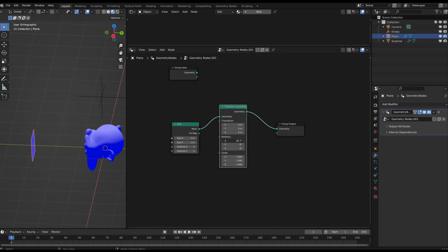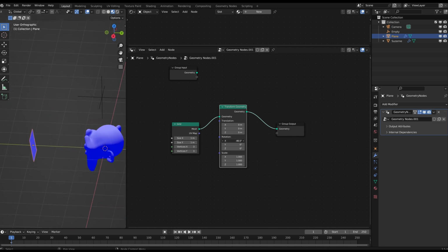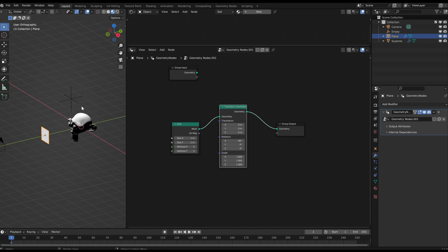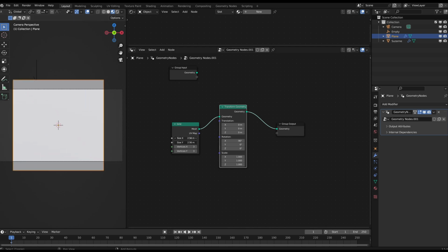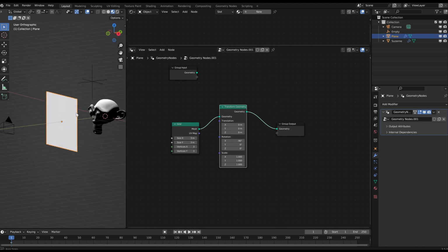Then I can see in which direction I want to rotate it, because I want to cast rays in this direction. So I want to use the blue face here, the correct face. So I use -90 degrees, and now it's oriented correctly. Now I want to increase the scale of the grid, because I want to display it basically here. So let's increase the size, maybe to this. That's okay. We could use 3 units by 3 units.